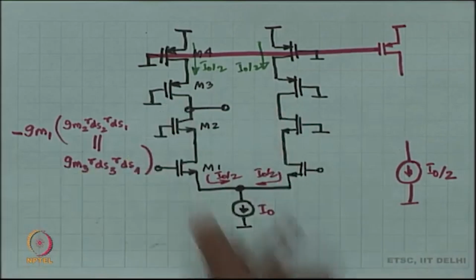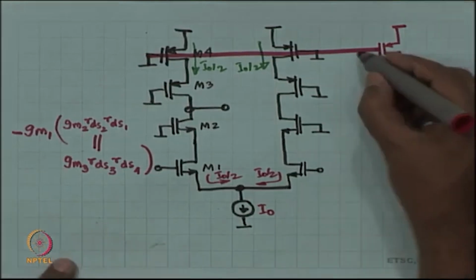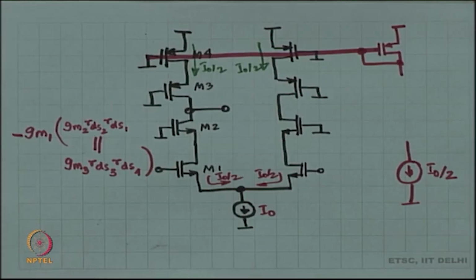What about M3? Are you going to ground? It is okay to ground, but ground is not optimal. Right, ground is not the optimal voltage. For example, you could have done a Wilson current mirror, you could have done a modified Wilson current mirror, you could have done